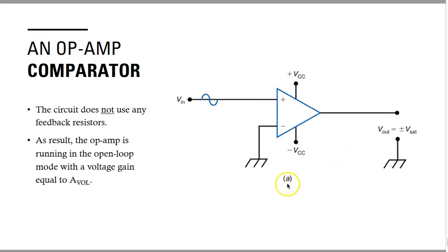This type of circuit can be used in analog to digital conversion, where you want to compare the voltage level, and based on that you want to send a signal. There you can use this type of comparator. For example, in this particular case, the inverting terminal is grounded and the non-inverting terminal is given some voltage level.